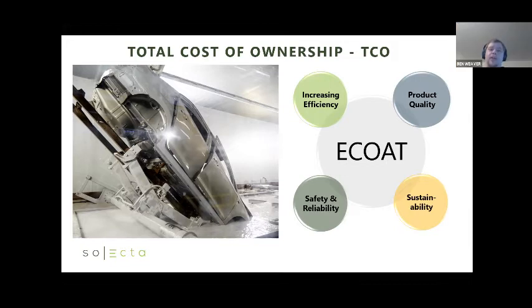Yeah, so typically the temperature and pH ranges are going to be more controlled by the paint bath and the specifications from the paint supplier. Now, typically in a paint bath, you're going to have 90 to 100 degrees Fahrenheit in there, and the pH is going to be probably between 4 to 5, because there's going to be quite a bit of acid in the paint bath. So that's going to be pretty common.